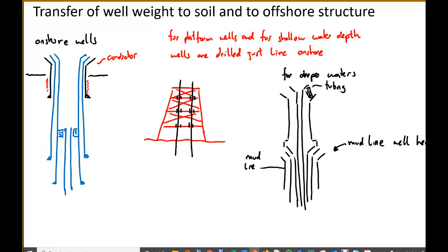Okay, so here you have the tubing. Remember that between all of these hangers we usually have some packer that avoids leakage. This is protecting, because remember the high pressure area is going to be here. If we prolong this part, this is exposed to the full pressure of the reservoir. The internal pipe, the tubing, and the production casing are made to tolerate that pressure. But the pipes outside are just for structural purposes. They are not made to tolerate it.